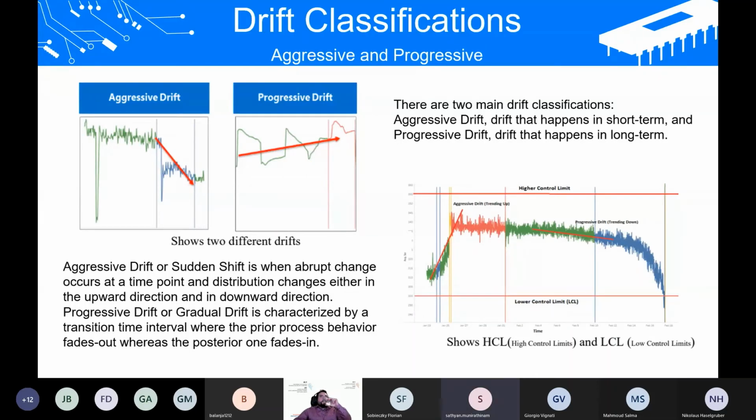It can go either down or up; both drifts can happen in either direction. That's what we want to detect. The goal is also to see how it's progressing, right? So we want to set different threshold limits within the drift. Hey, this is more of a warning. Hey, this is more critical, so that the technicians can react based on that severity.